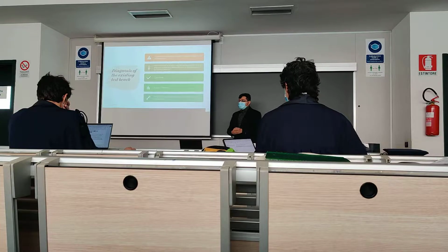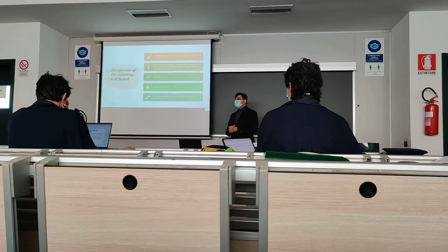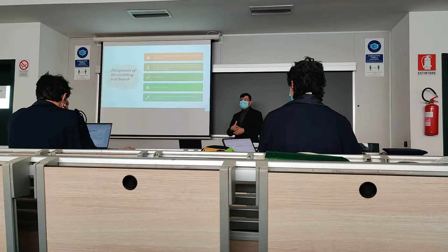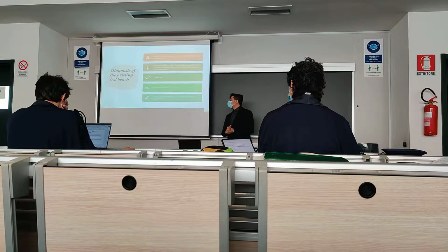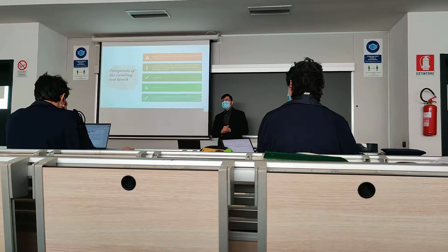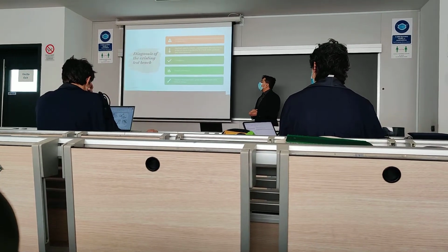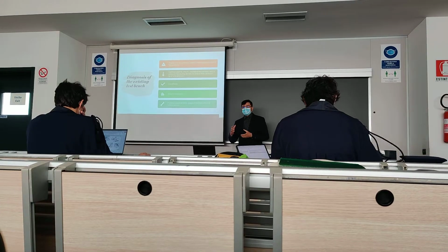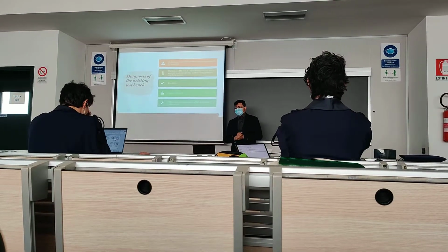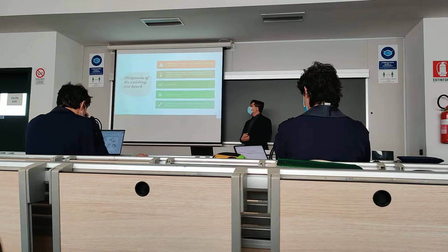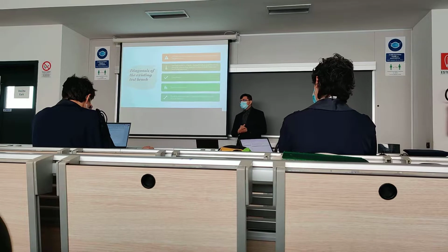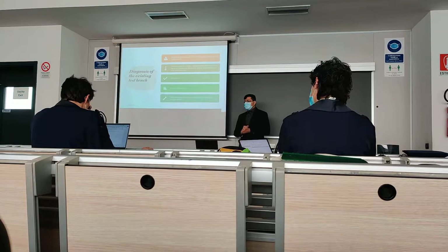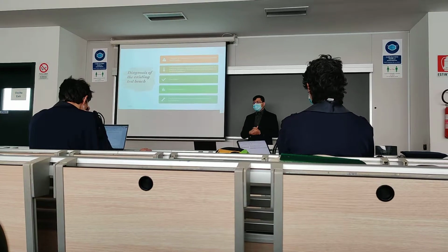Okay, before doing that, the existing centrifugal test bench was not in a proper condition because due to heavy wear and tear, a lot of inaccuracies were obtained. So first we tried to analyze where these inaccuracies were coming from. The problems we encountered mostly were errors in the pressure values and also in the torque meter. First we theoretically calculated the pressure values using the Bernoulli equation applied at the mouthpiece, and we found out there was a difference; it didn't coincide.